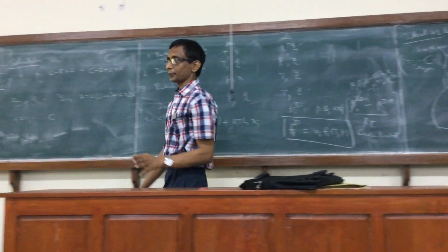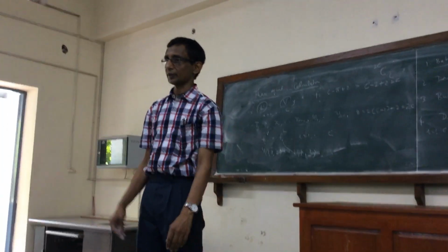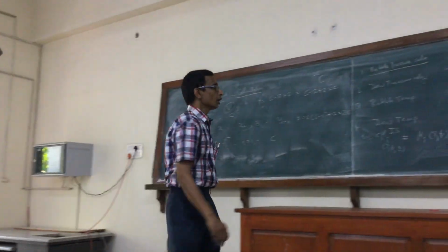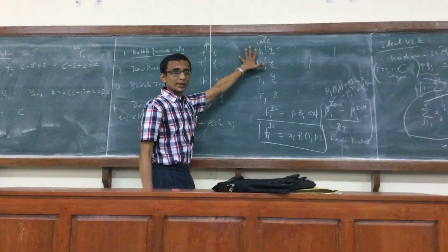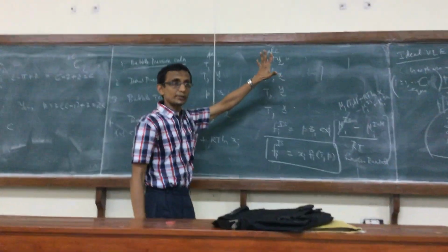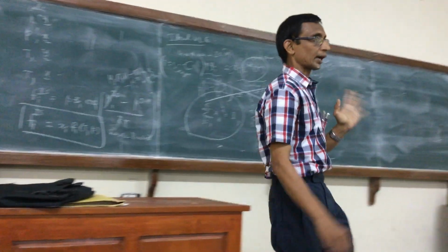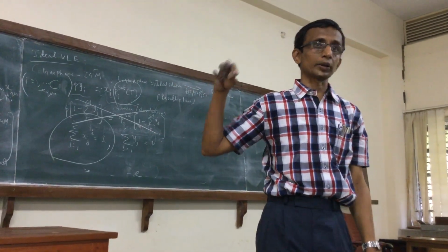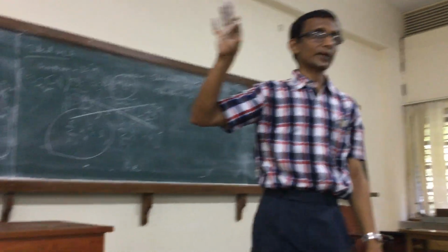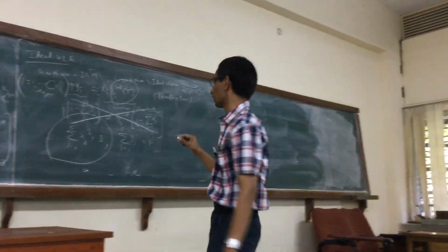We don't want to deliberately specify something that is not even satisfying the mole fraction constraint. That's absurd, right? However, you will see that the mole fraction constraint of y is also to be kept in mind. Sometimes it's not immediately verified. So you calculate the mole fractions of y and keep on with the algorithm and finally check whether in fact the calculated yi's satisfy it. It's very important. You cannot afford to forget this.